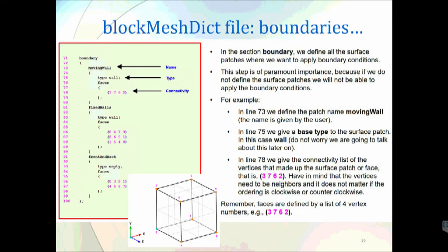And of course, these are the three different types of boundary conditions for our case. The example of a lid driven cavity. There is the moving wall, the top face, then the fixed walls, faces at the two ends. Okay, faces at this end and this end, and of course at the bottom. Okay, so these are the fixed walls. So you can see that fixed walls has three faces. Moving wall has just one face. Okay, and front and back, of course, this face and the one into the board. Okay, the rear and the front.